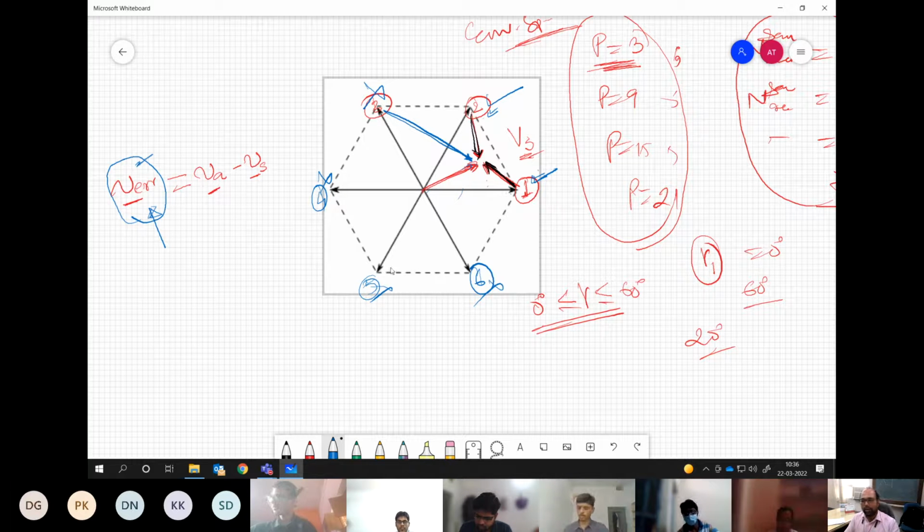Now, the next level, what I have been asking: yes, samples must be symmetrically placed. That is true. If you have only one sample to realize over here as the voltage vector and you keep it in the middle, say at 30 degree, you are going to have V1 and V2 voltage errors almost equal, and the magnitude is not very large. It is okay, can be considered. But if you try to have something over here at this location, your V1 may be small, but V2 will be very large.